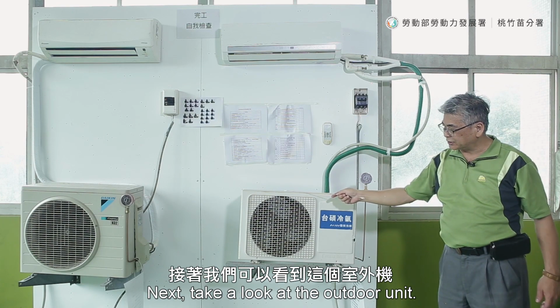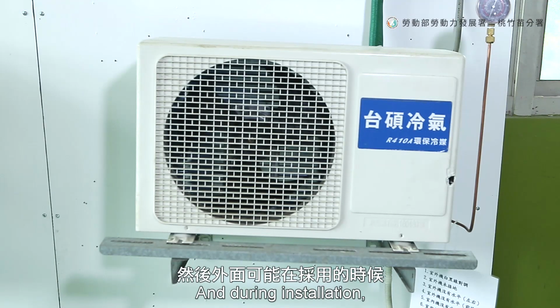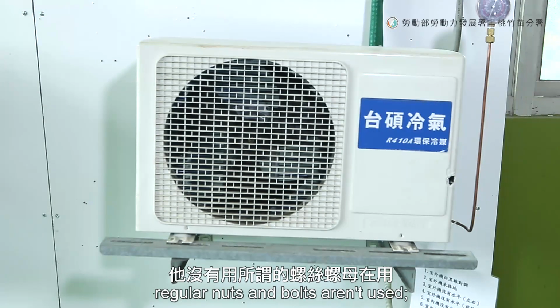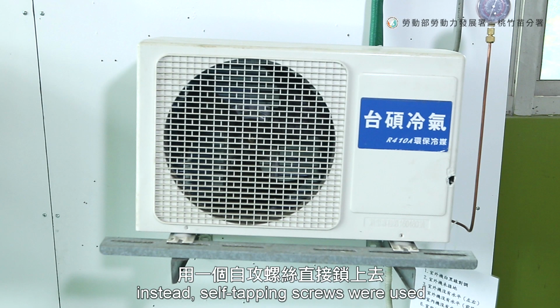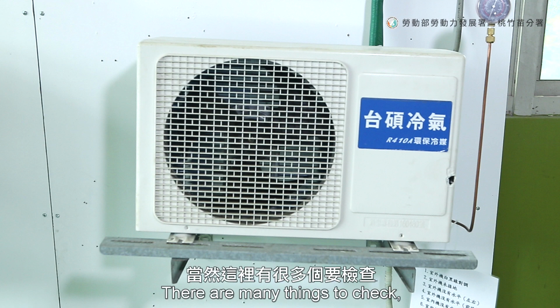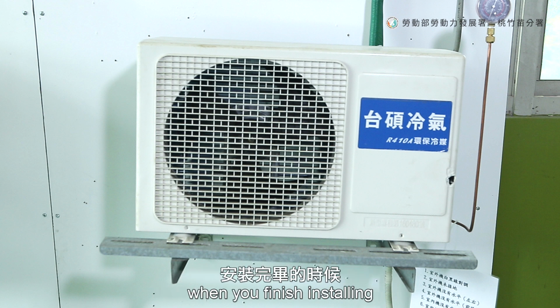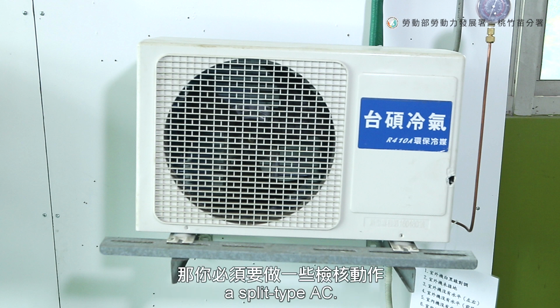Next, let's take a look at the outdoor unit. It's tilted and not secured. And during installation, regular nuts and bolts are not used. Instead, self-tapping screws were used and caused the tilting. There are many things to check, such as tilting. These are all among the checklist when you finish installing a split-type AC.